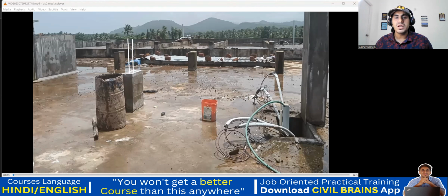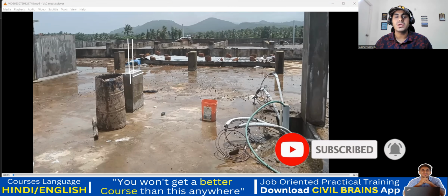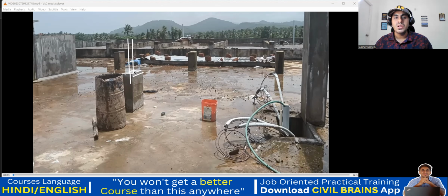Now how will you take care of this additional rebar? For that, we'll open up this top concrete. We'll just strip the top concrete, and we'll try to insert this rebar inside the concrete. You may ask, sir, how can you insert? We'll do the drilling and insert this much rebar inside this concrete, and we'll use nitro bond. It's a quick fixing chemical. With that we are going to lock it, and then you can raise the rebar. So that also can be done.